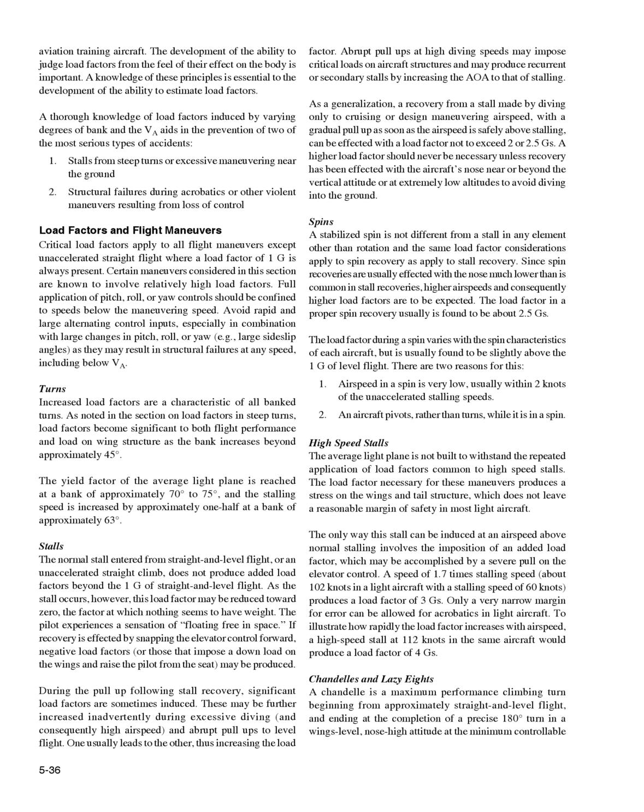Critical load factors apply to all flight maneuvers except unaccelerated straight flight, where a load factor of 1 G is always present. Certain maneuvers considered in this section are known to involve relatively high load factors. Full application of pitch, roll, or yaw controls should be confined to speeds below the maneuvering speed. Avoid rapid and large alternating control inputs, especially in combination with large changes in pitch, roll, or yaw, for example, large sideslip angles, as they may result in structural failures at any speed, including below VA.